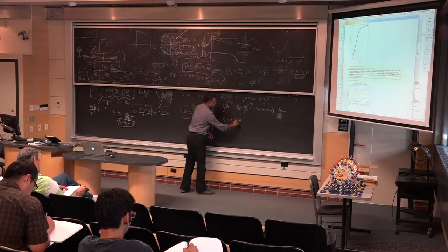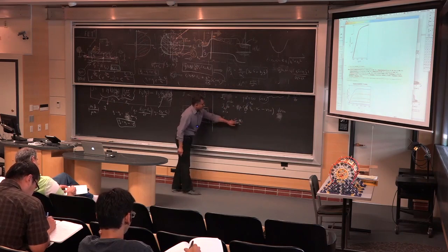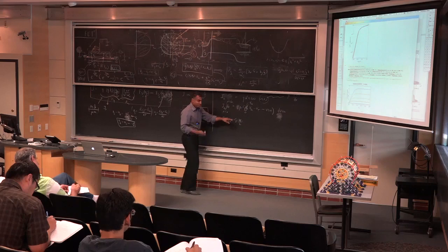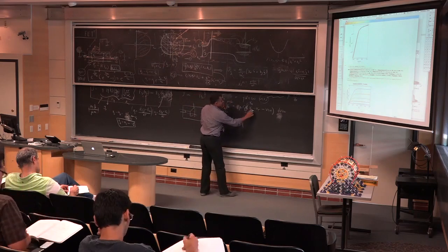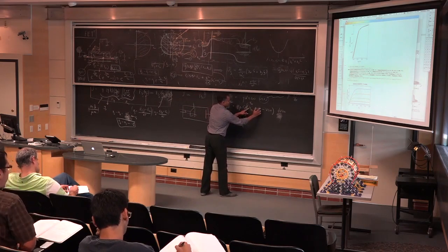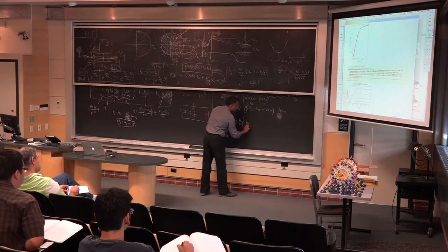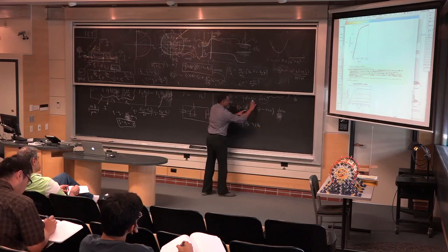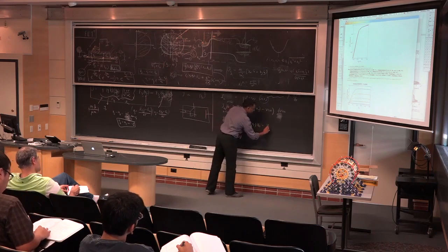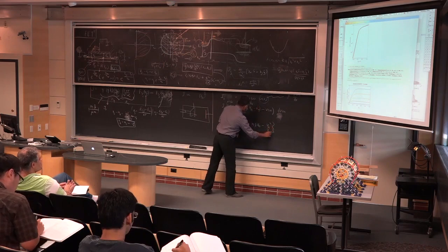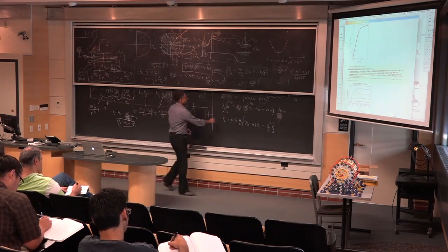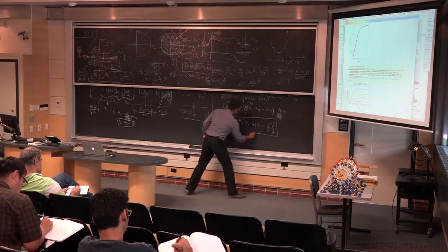If you have done any classical semiconductor physics, this W by L appears again and again, width over L. If you've done any CMOS design, it appears very often. The integral here is trivial too. VGS minus VT is a constant, so you get VGS minus VT times the drain voltage, minus VDS square by 2. So that's your current. That's Shockley's theory of a long channel transistor.